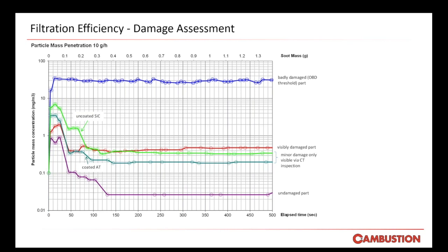A second question we had is, so all we've shown here is uncanned parts that we put straight in the filter test adapter. Another question was, can we test whole exhaust systems? We can indeed, and there are plenty of specific applications that we haven't talked about here, where you might want to test a whole canned filter, or put the whole canned exhaust system, including maybe the filter and the catalyst, in there. If we take the FTH out of the test section of the DPG, then you can put any kind of exhaust system in there. We'll provide the flanges, and it's just a welding job.